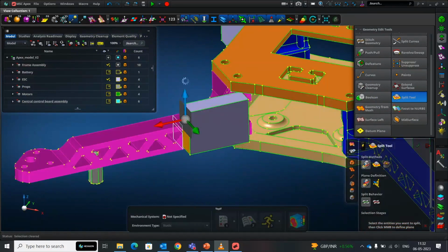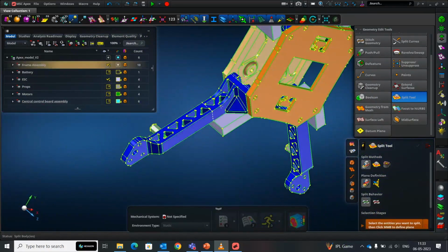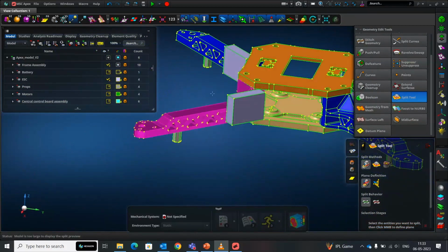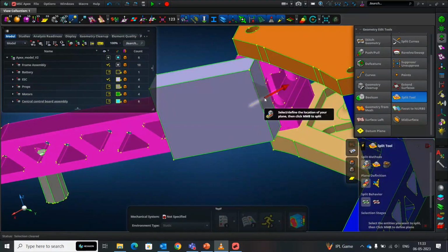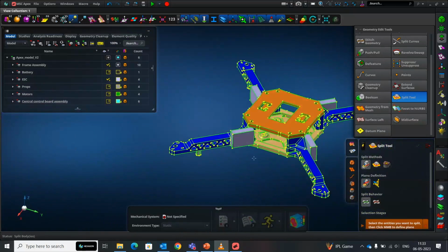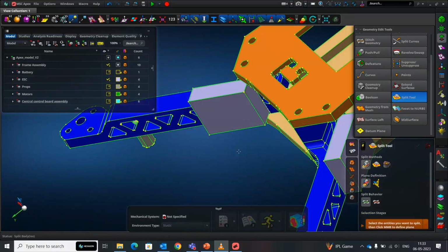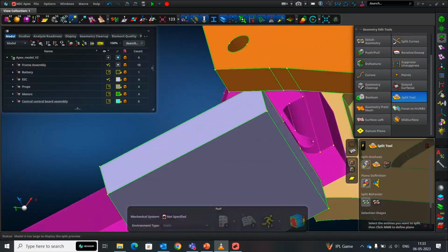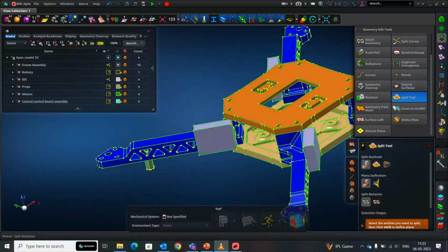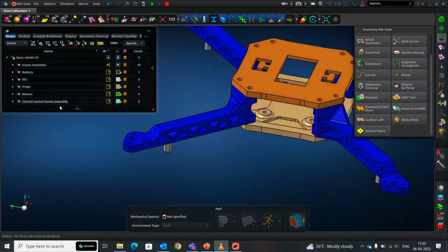I'm representing these non-structural masses, that is, whatever components are not going to participate in the load bearing capability of my airframe. They're going to be represented as structural masses in the form of points. So they're not going to take any kind of density. They're not going to take any kind of stiffness. But what they are going to represent is a block mass that's going to behave over there. So we will soon see how I'm going to do that. Firstly, I partition these regions such that I can mesh this structure, and I can also go ahead and assign the mass for those structures as well.